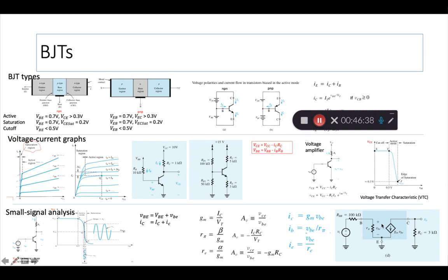So this is the small signal model, and if there's a load resistor R_C or other resistors, they all get connected here, and you can solve some problems using simple KVL and voltage divider methods because you have drawn the small signal model. Okay, so that's the benefit of having the small signal models to help us solve problems.